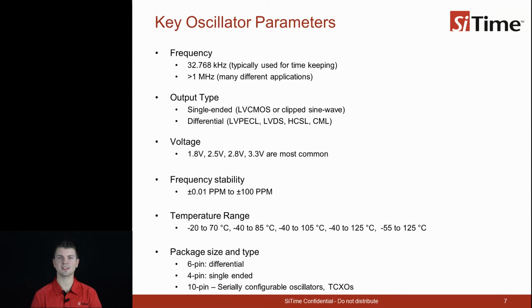There are several differential signal families. The most common differential signal families are LVPECL, LVDS, and HCSL. They all have voltage swings in the 700 to 800 millivolt range, and the major difference among them is DC offset. LVDS has a reduced swing at 350 millivolts to 450 millivolts.